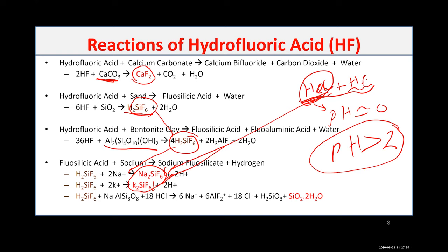So if you have carbonate, HF will directly react with the calcium carbonate and produce calcium bifluoride, which will precipitate. That's why we do not always start with HCl, HF. We start with HCl first. And the idea here is to remove any carbonate, dissolve the carbonate before the HF, then behind it with HCl, HF to dissolve the silica, and a post flush of usually HCl to keep the pH 0 and push all the reaction product deeper inside the formation, away from the near wellbore, and that will at the end give you overall enhancement for your production.